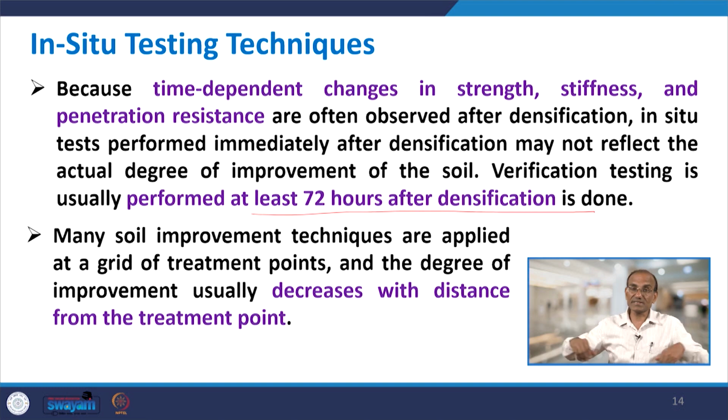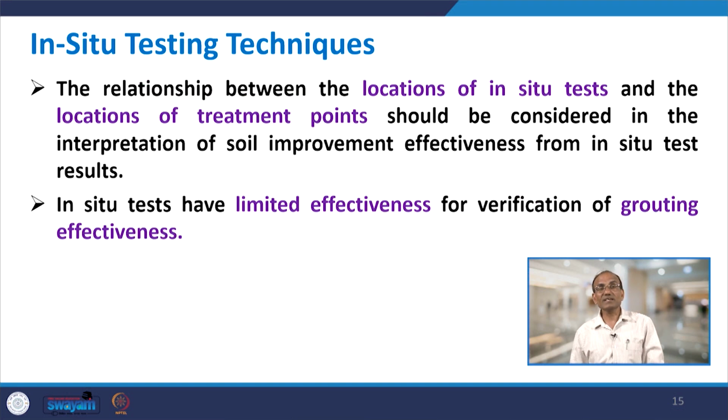When you do the densification, you do it in a grid pattern: you apply load here, densify, and then move to another point. So, naturally the densification will be more effective near where you are doing the treatment. As you go away from the point of treatment, the effectiveness will decrease. The relationship between the location of the in situ test and the location of treatment points should be considered in the interpretation of soil improvement effectiveness from the in situ test. Particularly, these tests will have limited effectiveness if you want to verify grouting effectiveness.